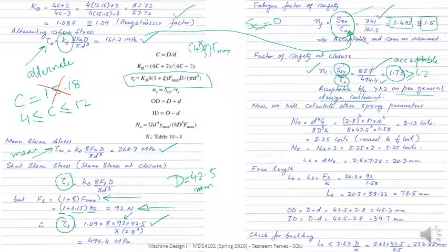So we proceed further. I know the wire diameter, I know the G, I know the mean coil diameter, I know the spring rate. I can calculate the number of coils. This is the number of active coils. Now look at it over here, 5.13, and let me go to this rule again of one quarter, meaning 0, 0.25, 0.5 and 0.75. So this is between 5.0 and 5.25. It is closer to this one, so I'm going to round off to this. So when I round off, I get 5.25 coils.